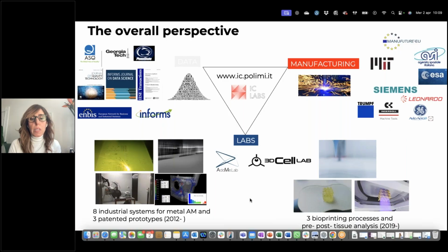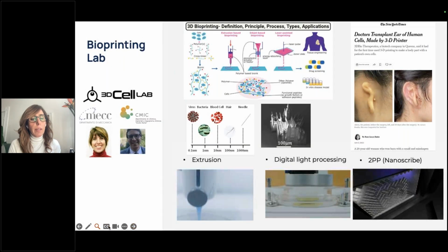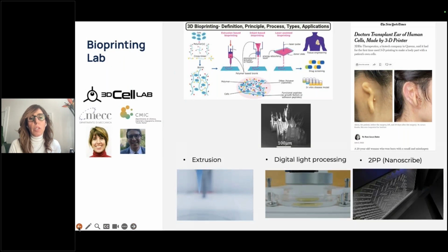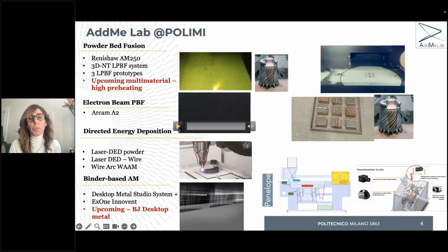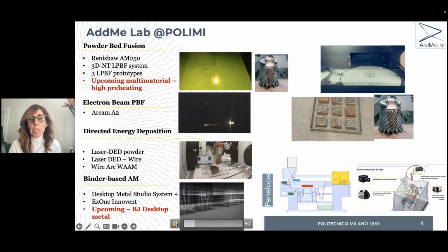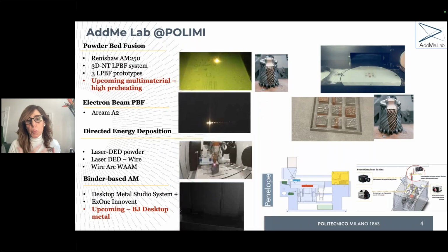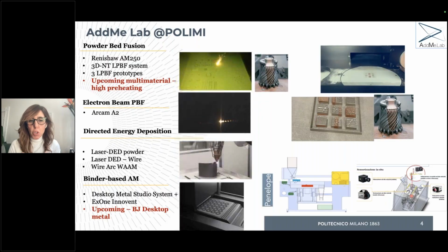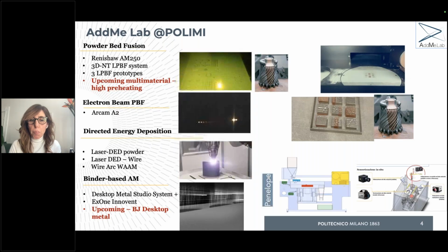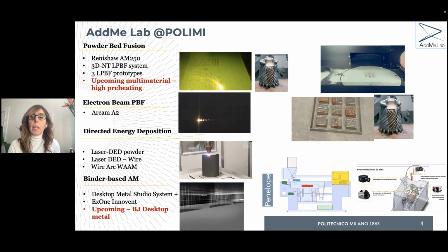So the main difference is that additive manufacturing traditionally works with a lot of different metals. And so here are all the solutions that we have in our lab. As you can see, the process is quite open, and can have many different principles for spreading powder and melting powder, which means at the end being able to create really complex shapes. And we will have some time discussing what this complexity means from the viewpoint of quality.